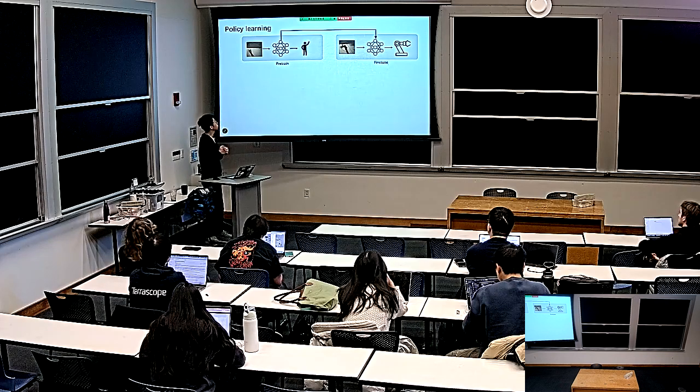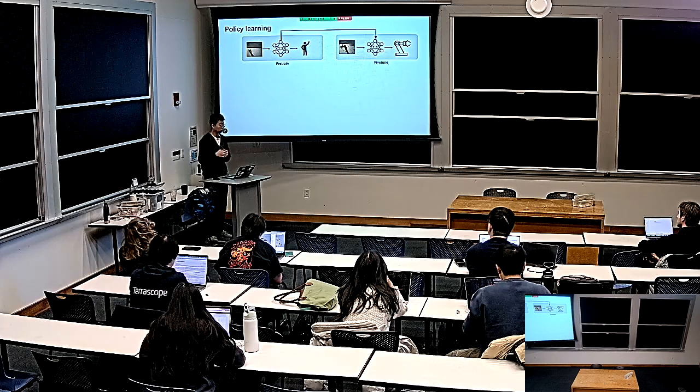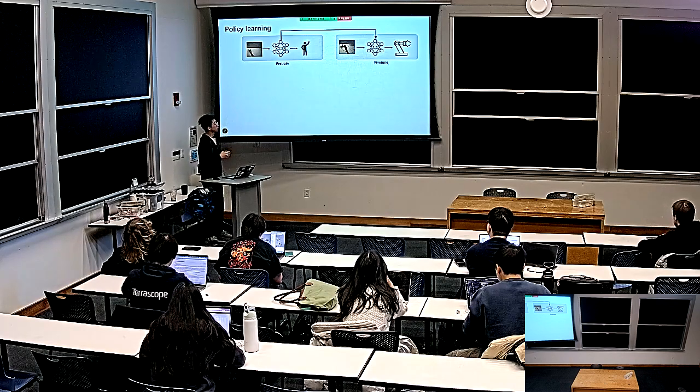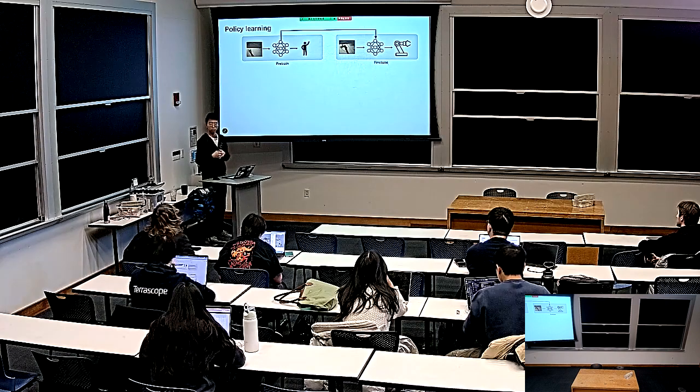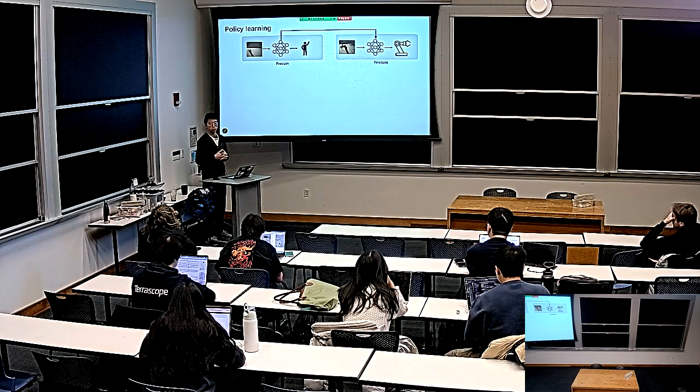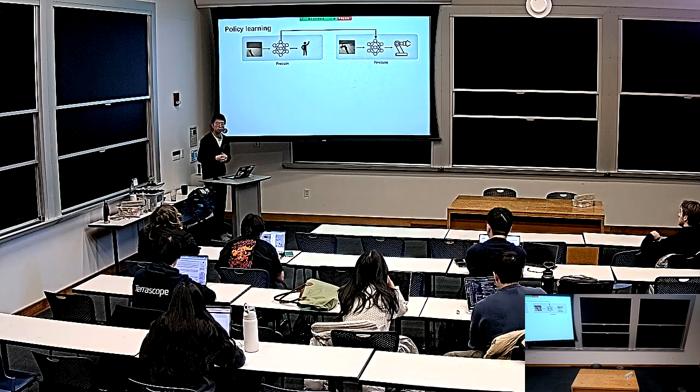The first way is to pre-train a policy based on human video and human action. Then we fine-tune this network based on the robot data, which takes the robot observation as input and outputs the robot action. The former dataset is collected by the method we just introduced from online video. For the dataset used for fine-tuning, we still need to collect data from teleoperation, which was introduced by Hyung-Hyo on Monday.